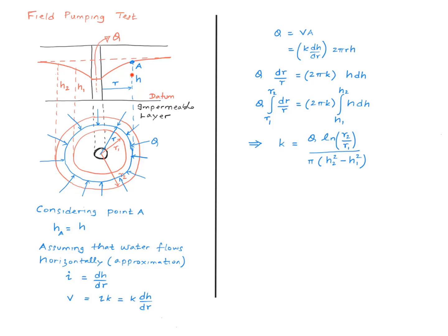So if I can figure out the velocity at which the water flows into the cylindrical region, then all I have to do is to multiply that by the surface area of the cylinder in order to get the rate of flow into the cylinder. And that's the quantity that comes out as you keep pumping. So we do make a number of approximations here.